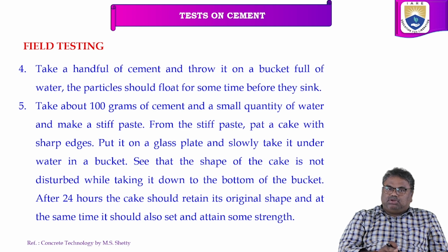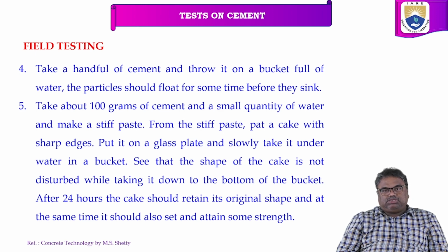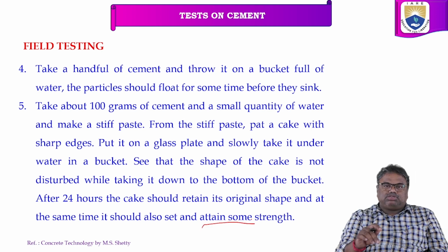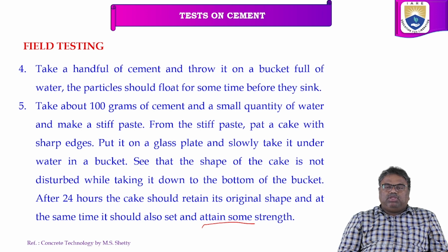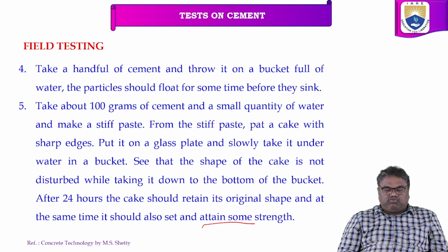After 24 hours, the cake should retain its original shape, and at the same time, it should also set and attain some strength. Why does it attain some strength? In the previous class we discussed the hydration process, right? Once you mix water with the cement, the hydration process takes place.